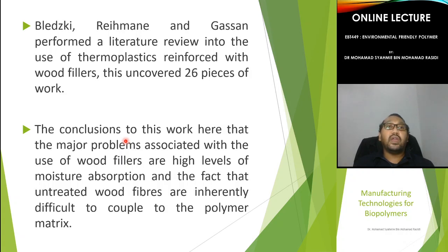The conclusion to his work is that the major problems associated with the use of wood filler are high levels of moisture absorption and the fact that untreated wood fiber is inherently difficult to combine with the biopolymer. This is the major problem when you are using natural filler such as wood filler.